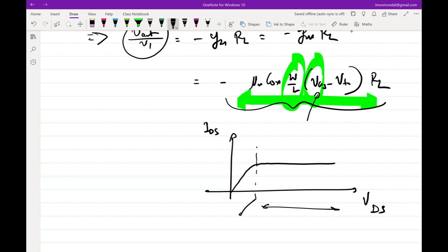Okay. And this region is VGS. Let me call this VGS1, because for a certain value of VGS1, you have got this gain. Now I say that I'll increase my VGS1 to get more gain. If you increase your VGS1, what happens to the ID-VD characteristics? Let's say, this is VGS1. What do you think will happen to the ID-VD characteristics if I increase VGS1 to, let's say, VGS2? This point will shift, but what will happen to the entire curve?